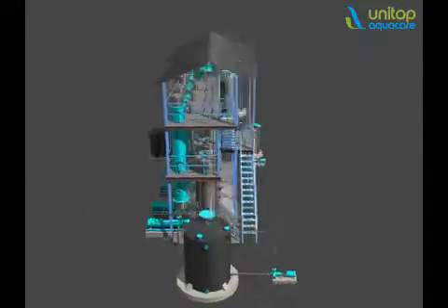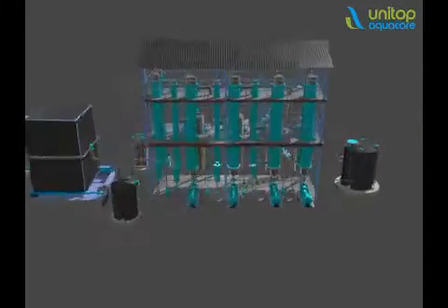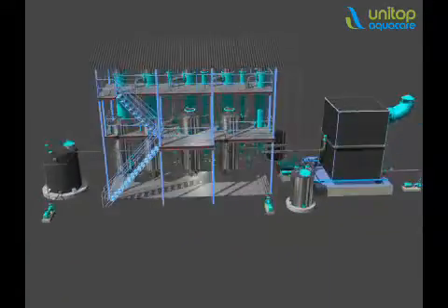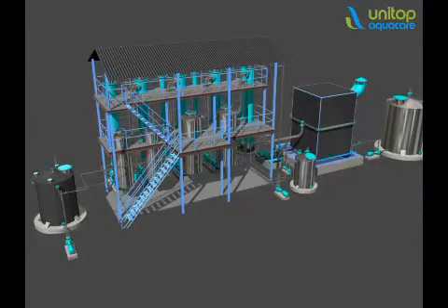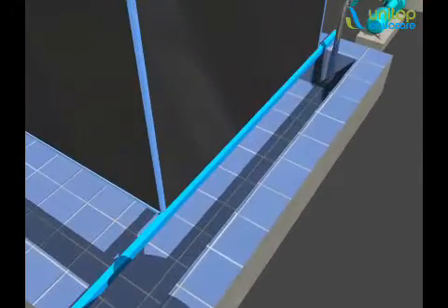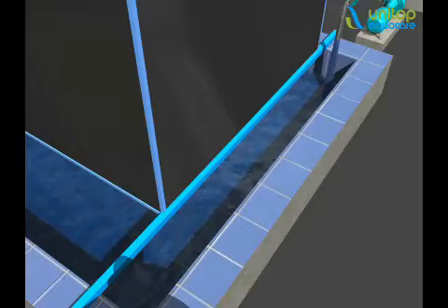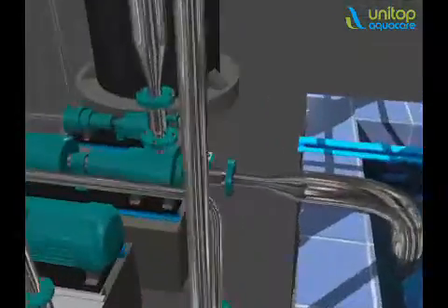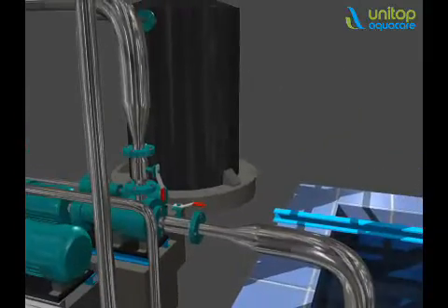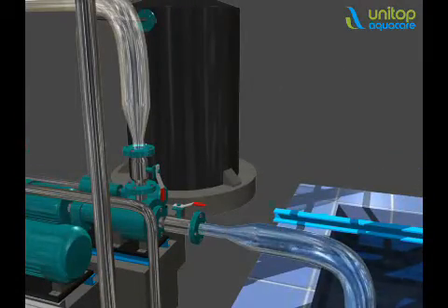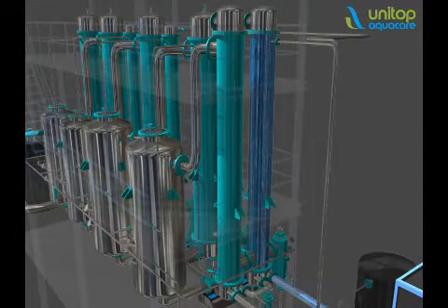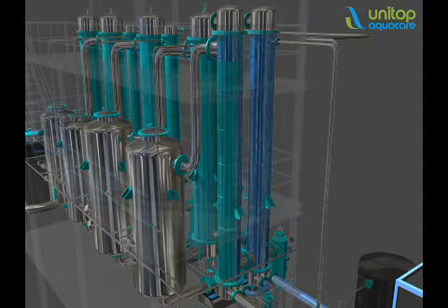Commissioning of the multi-effect evaporation plant to achieve zero liquid discharge as per pollution norms. Adiabatic evaporator. RO reject is fed to the adiabatic tank. From the adiabatic tank, the RO reject is pumped to the surface and vent condensers. The condensers are used to condense vapors in the last stage of the evaporator to maintain the required vacuum in